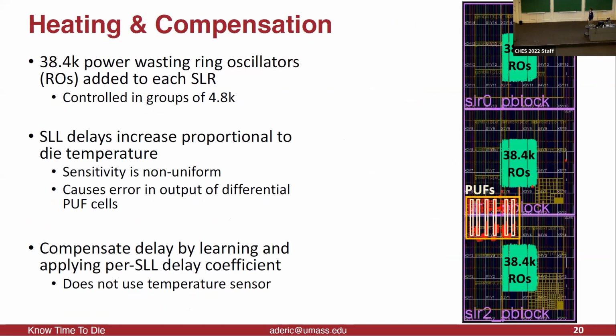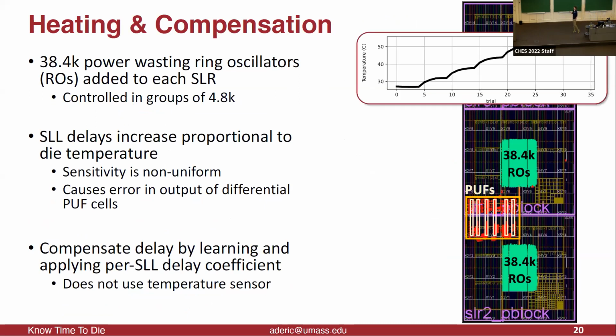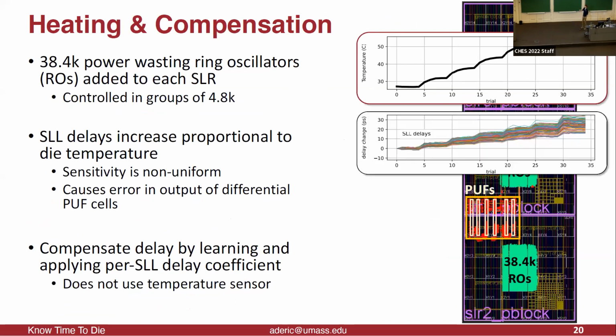And we had a lot of them, but you could turn them on in groups. Once we tried doing that, you can see that the temperature of the die actually goes up, and so delays also go up. But what's interesting is that not all of them go up by the same amount. Some of them increase much more than others.